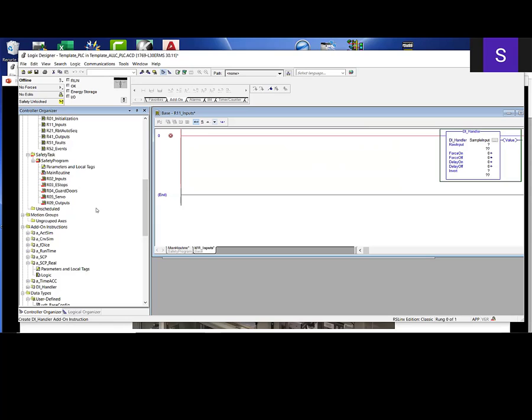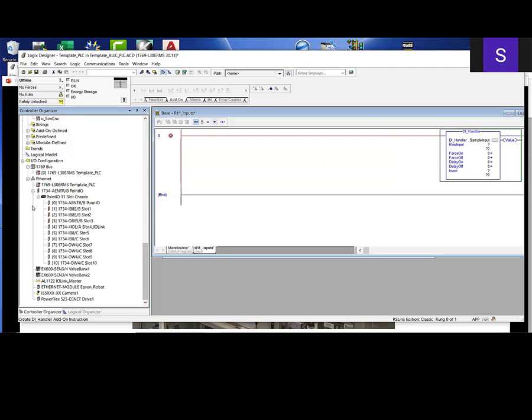I want to say it had 8 to 10 safety inputs in that little Sweet Machine. And that's to stop people from getting hurt, right? So it's got safety control even for the robot. So if somebody hits the e-stop, it pulls the power from the safety relays and drops the power to things safely. So that safety task reflects a lot of that. And that works hand in hand with this safety capable PLC. And for Allen Bradley, they put just a little bit of red in here. And that's kind of how you know it's a safety device.